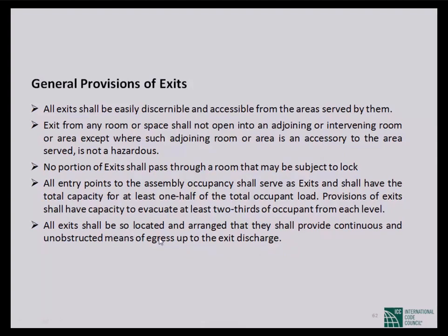All exits shall be located and arranged so that they provide a continuous and unobstructed means of egress up to the exit discharge. Sometimes, when coming down from the top floor to the third or fourth floor, they change the stair and give a horizontal movement to a different stair. It should be avoided. If you use a fire stair from, for example, the 6th floor to the 4th or 5th floor, then somebody moves horizontally from that stair to another, different stair.